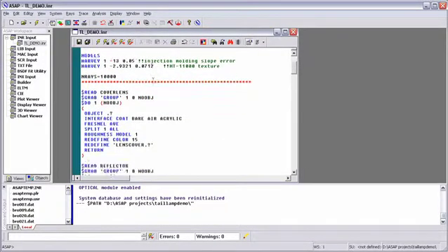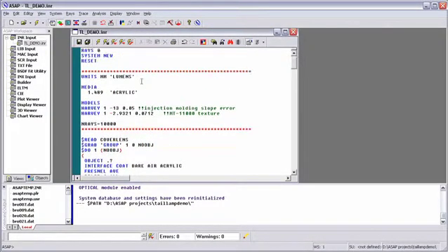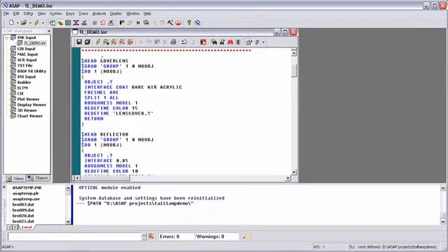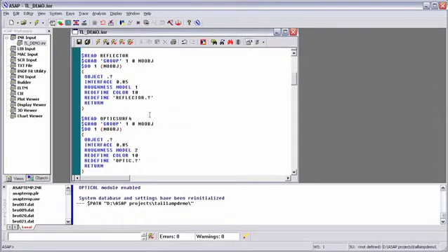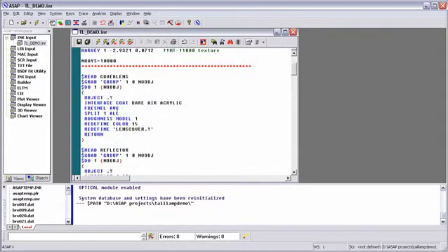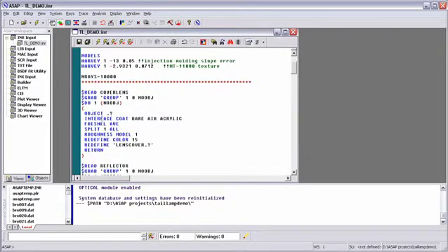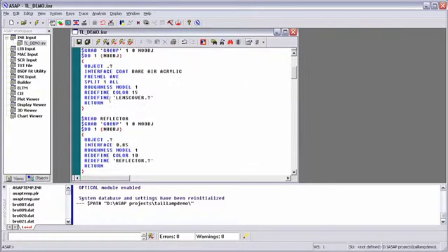I've set up my script file ahead of time to simulate the part, and we're going to simulate the cover lens, the reflector, and the optical surface that we just created. One of the things I mentioned before is that we skipped the material assignment in the IGES translator, because inside my script in ASAP I can use this construct, the do-lib construct, that allows me to set my material properties for each one of those components.